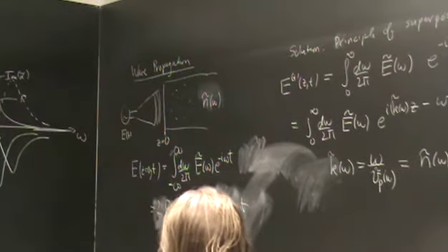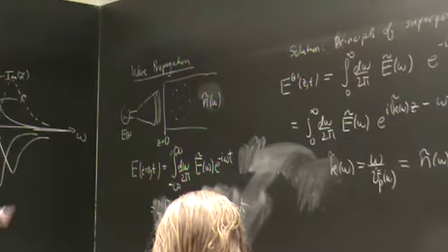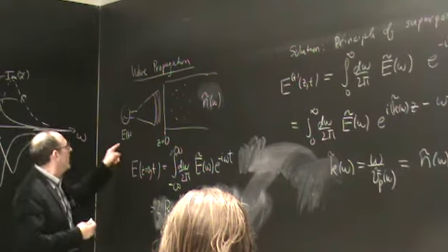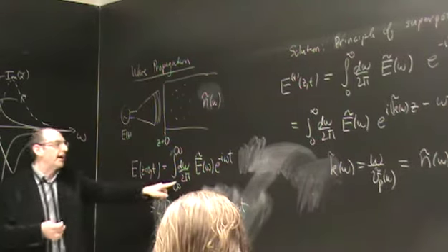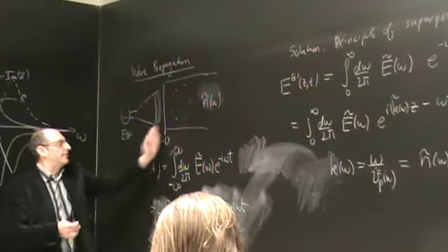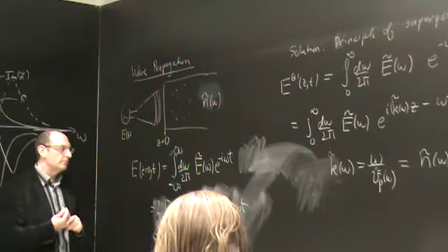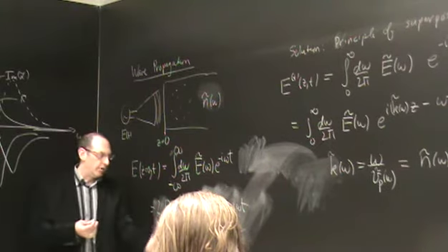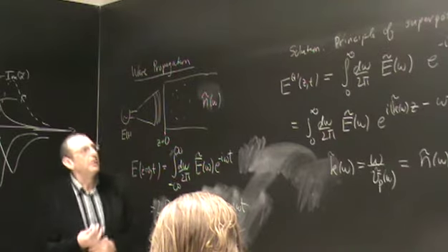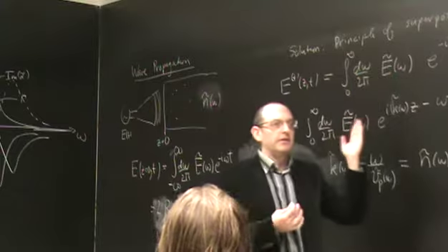And so we can write down a formal solution to that instantly by using Fourier analysis, because we can take our initial signal, break it up into its Fourier components. That represents the signal at the input phase at z equals 0, which I've written here in terms of the positive frequency component. And then we know what the solution is for each frequency component.